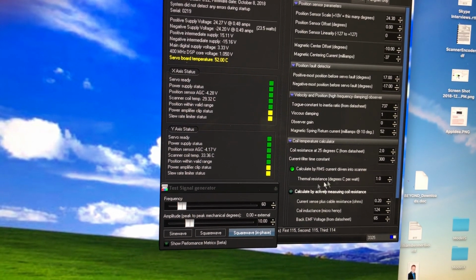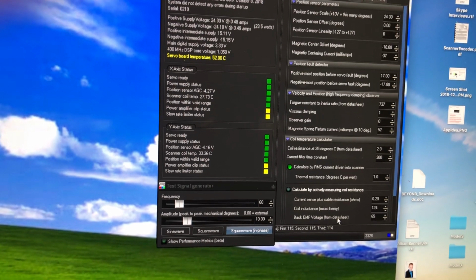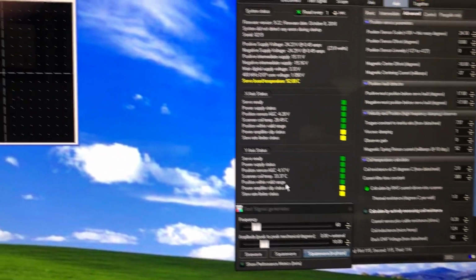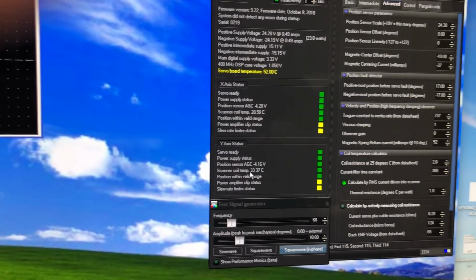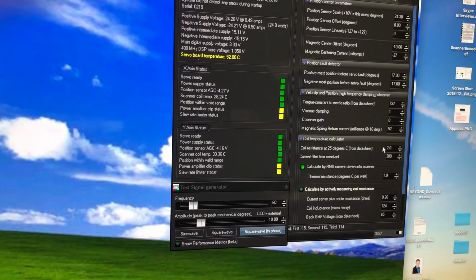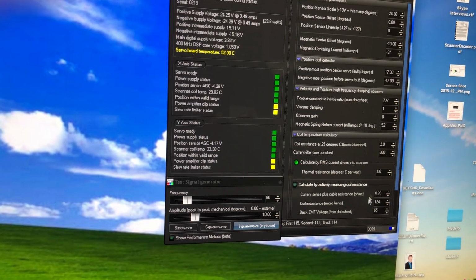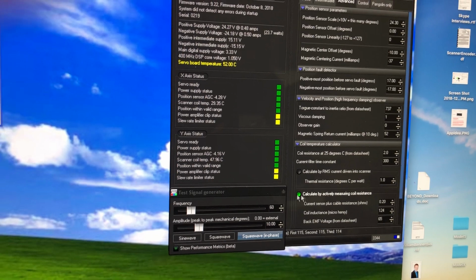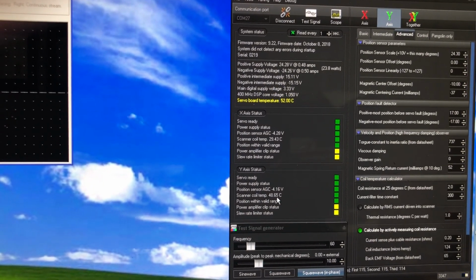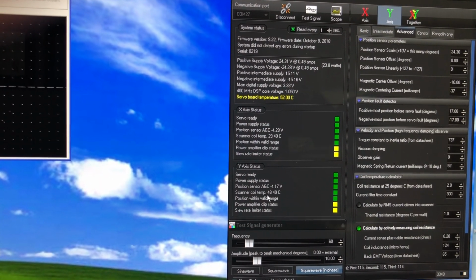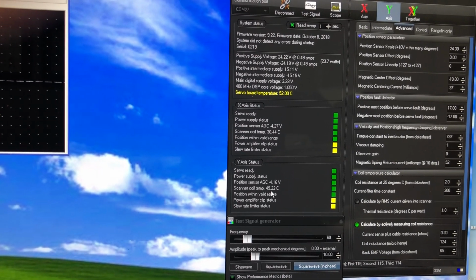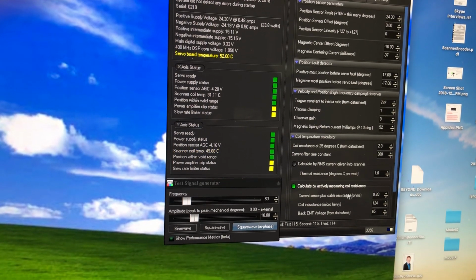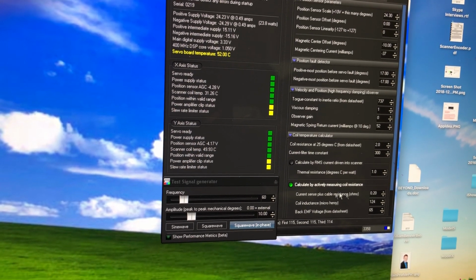The purpose of this video is to show what you need to change if you change the cable and if we actively select this. So you see now we're sitting here at 33 degrees. And remember I said that this is completely insensitive to cable length. Well, if I click on this one, all of a sudden this thing thinks that the temperature in the scanner is almost 50 C. And the reason is because a 3-meter cable has a lot more resistance in it.